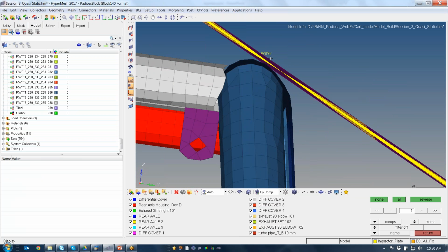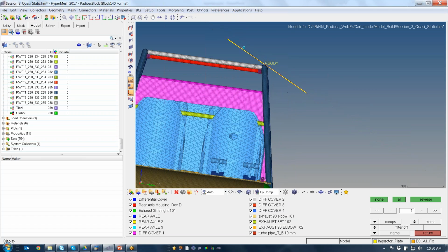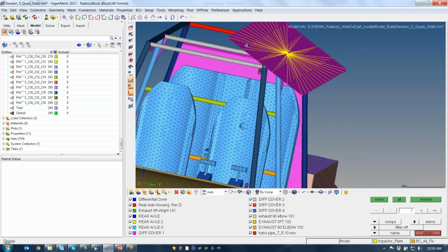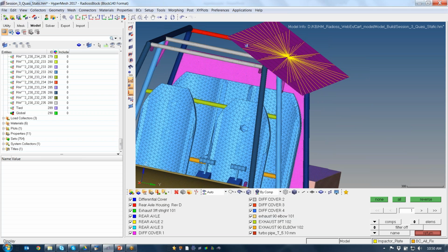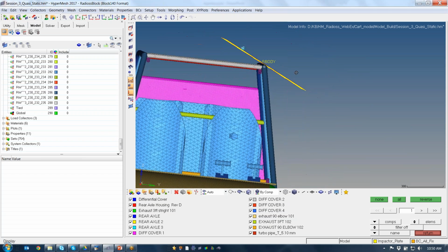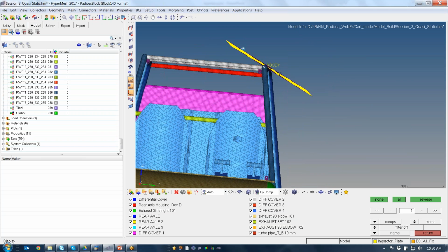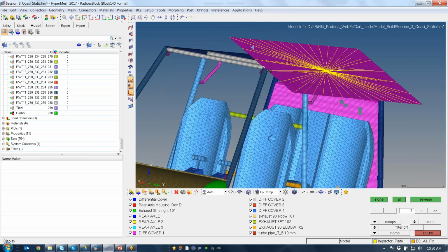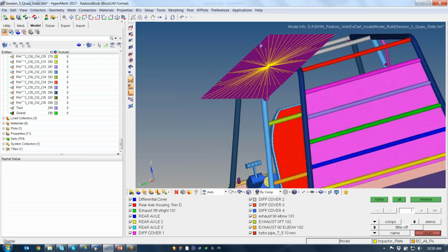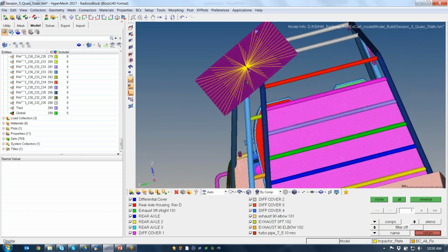It's a surface to surface contact, and this can work well with type 7 of course. But just to have the variety and just to show the demo of how to create the type 11. So I'm taking this region. I have a curved surface and a flat plate, so maybe type 11 will work more efficiently than type 7. That is one reason.